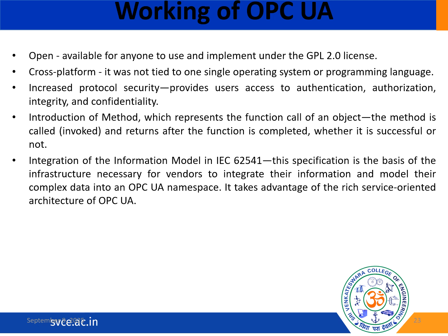However, since OPC DA relies heavily on the Windows Distributed Component Object Model, many vendors have recognized that OPC DA is not truly an open standard, and it behaves poorly in a disconnected state. It does not work well with firewalls, and it only works in Windows.